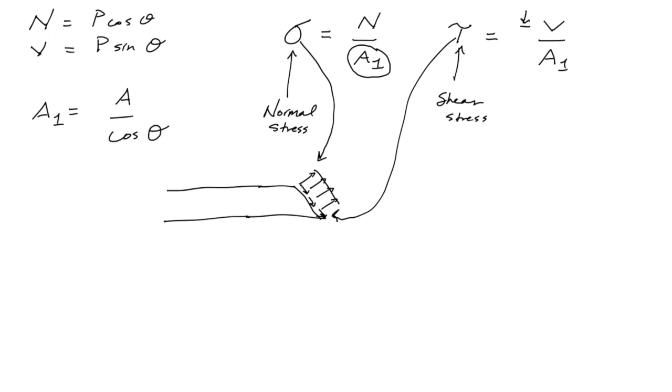Notice that this force is going to tend to bend this bar into something that looks like that. This force is going to want to make a frowny face out of this bar, and we call that clockwise bending, and so that's a sign convention.